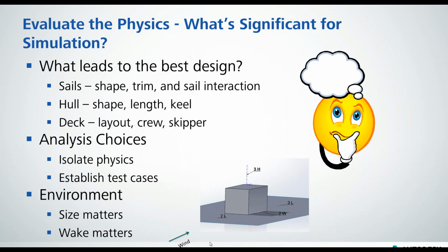Now, why do we need this? It's because the wake matters. If anybody's been on an airplane trying to land at one of our bigger airports or something like that, you might have to do an extra loop around the airport, flying around, while you wait for the wake turbulence to clear. That wake turbulence is from the plane that landed in front of your plane, and that wake is real. It's not a simulation artifact. It is very real, and a plane that has landed can leave a wake that is still settled over the airport that can affect the plane that you're in, and that's why airports have to have such timing to space out the planes so that the wake can dissipate.